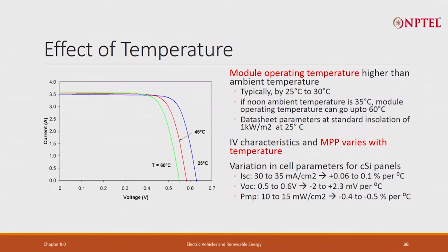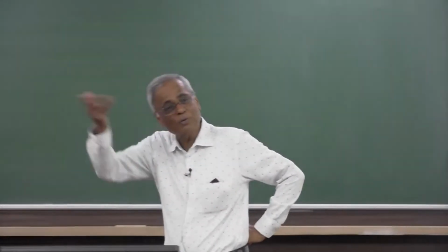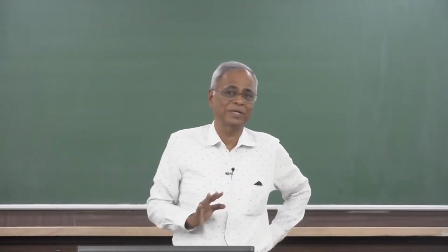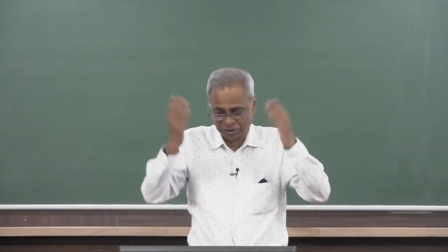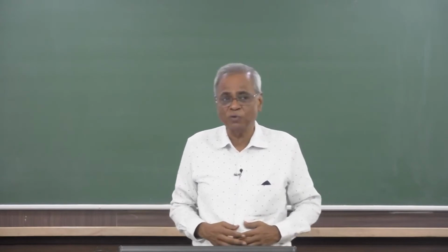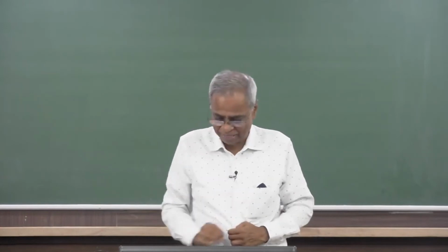Now, this is very important. In India, if there is a hot sun, it will operate at higher temperature. So, higher temperature will not give you the rated power, it will give you less power. That is the loss that you will get. I know my colleague Anson is struggling, why am I getting less power from the IITM Research Park rooftop? Very often the temperature becomes a very important corrective factor.